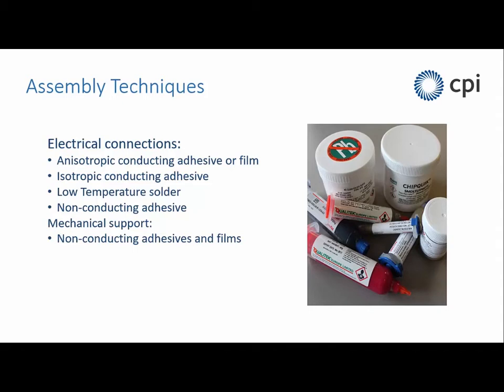One of the challenges with the materials that we work on is that these are all relatively low temperature materials. So PET can tolerate up to around 120 degrees centigrade, something like that. If you go much above that for too long, then it will start to wrinkle and deform. PEN can go a bit higher, which is really the only reason we ever use it.